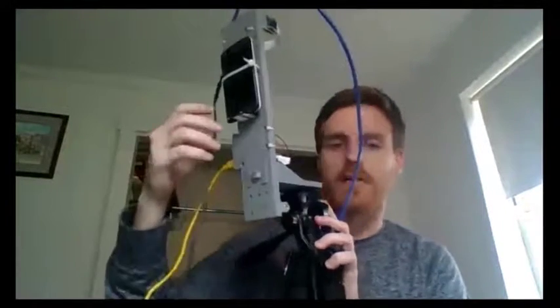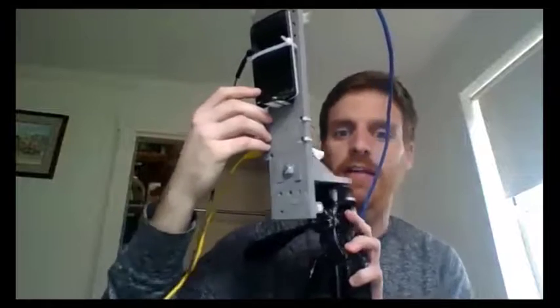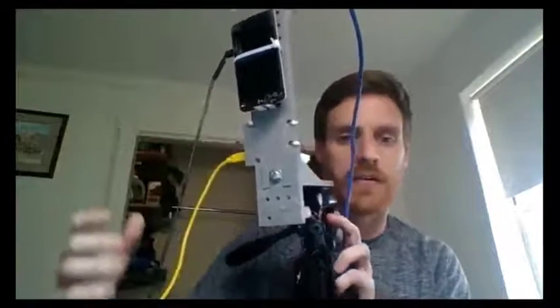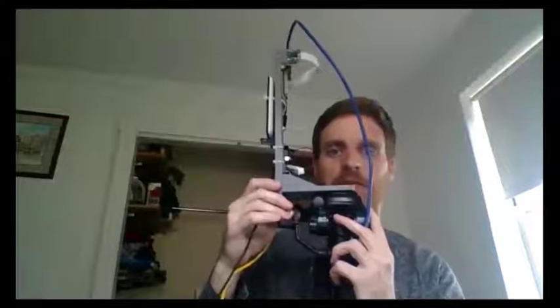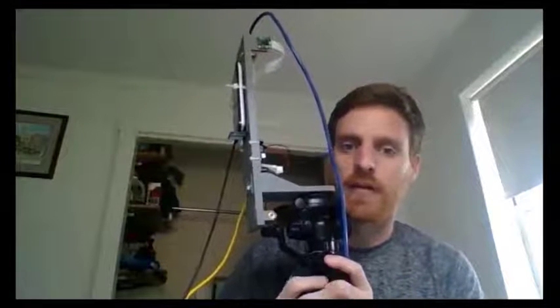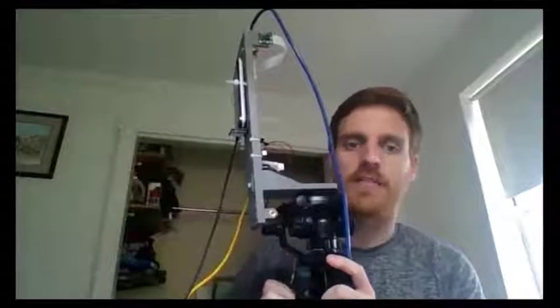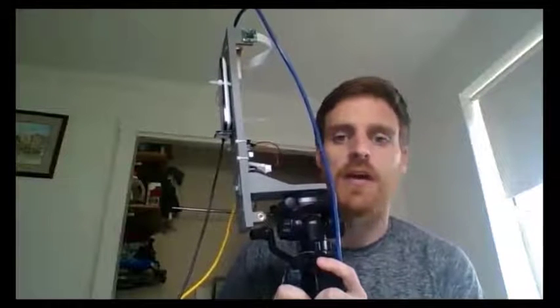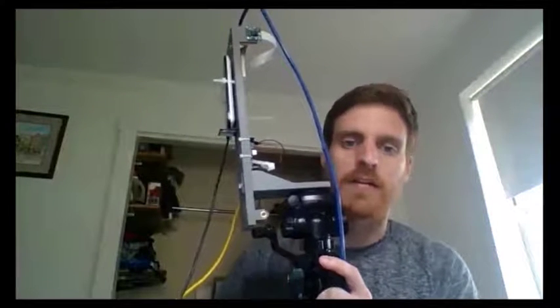On the other side of the LiDAR is an old cell phone. The cell phone has a leveling app that has been calibrated to read 0 degrees when the LiDAR itself is in the vertical position. As the LiDAR is panned up and down, this level app reads different degrees measurements. Coupled with the image of the laser interacting with an object, these degree values allow us to develop a full 3D definition of XYZ coordinates for each of the locations where the laser beam interacts with our object of interest. As we pan the camera, we build a series of 3D coordinates that can then be used to create a 3D point cloud or an overall 3D virtual representation of the object.